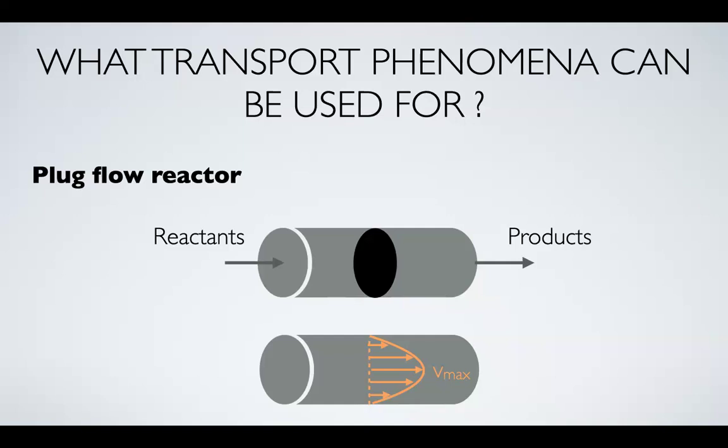So in terms of the rate of reaction, if you took the kinetics class before, you know that rate of reaction can be calculated across this cross-sectional area, and it's an average. The rate of reaction that you calculated is actually averaged across this cross-sectional area, but in reality, the rate of reaction across this area is not the same because the velocity profile is not uniform. Do you know what I mean? Any questions about this?